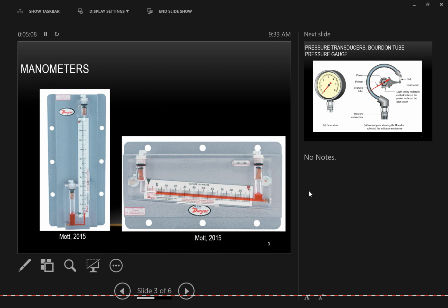And you got to know how to do this first, because later in the semester, we're going to show you how to calculate volumetric flow rate, and we're going to do an experiment down in the lab with Venturis, and you have to know how to calculate the change in pressure. As long as you know the change in pressure between 2 points in a pipe, you can convert that to how fast the fluid is moving. Very important for pump flow and pump sizing and all that. Okay. So those are more of a mechanical liquid level changing.